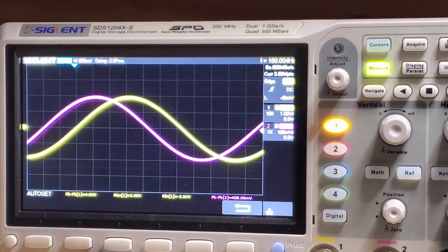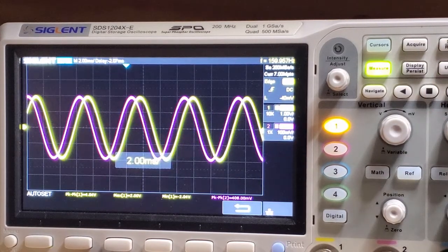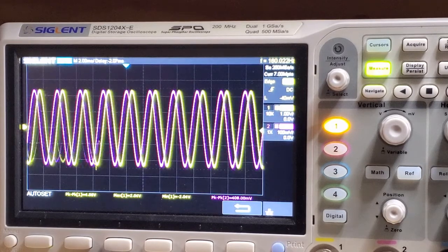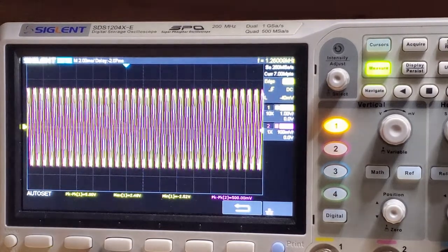So that's obviously a problem that you have to figure out in the radio, either by filtering out the frequencies, or increasing the number of taps. As you increase the number of taps, that response towards 0 hertz gets better. But that's definitely something that is a problem for this type of radio. So let's just go back up to where we know we're getting a good filter here.